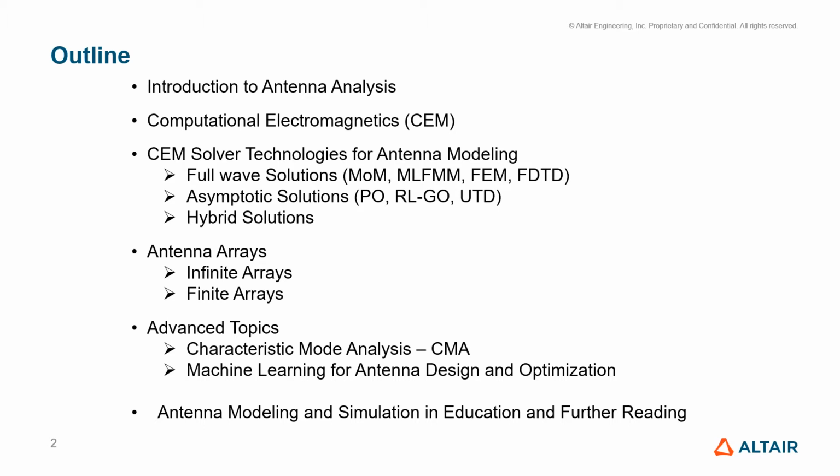Then we'll talk about antenna arrays, one with infinite arrays, that is using periodic boundary conditions. And then we'll also look at finite arrays with a special technique called DGFM. Not very well known, but I think it's a very effective method for simulating finite arrays, taking the mutual coupling into account as well as the edge effects. Then we'll briefly touch on advanced topics like characteristic mode analysis and also machine learning for antenna design and optimization.